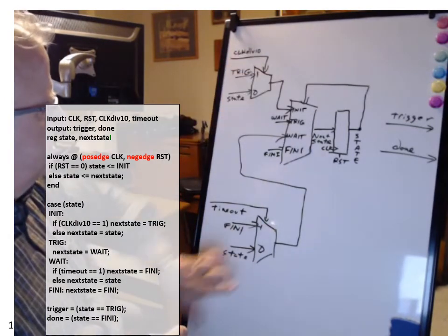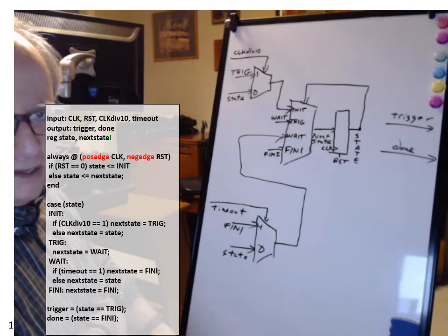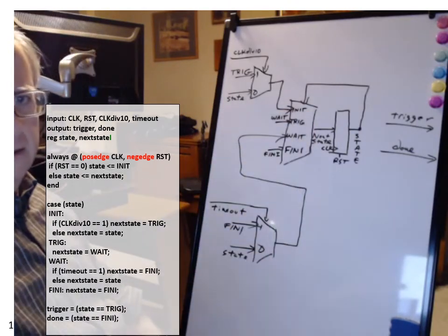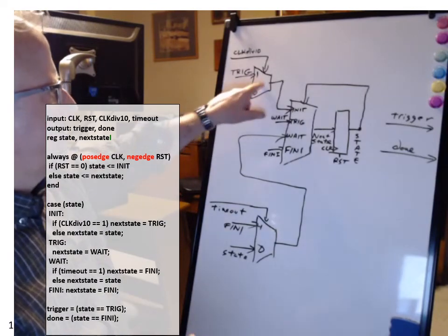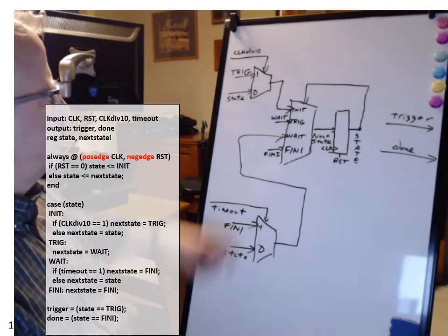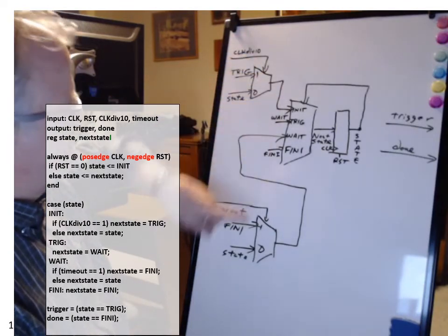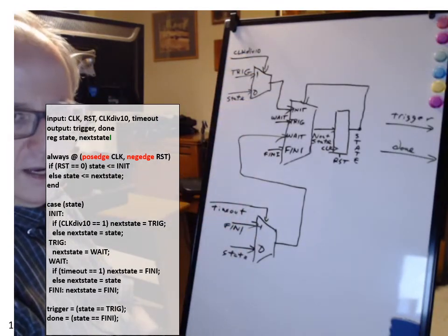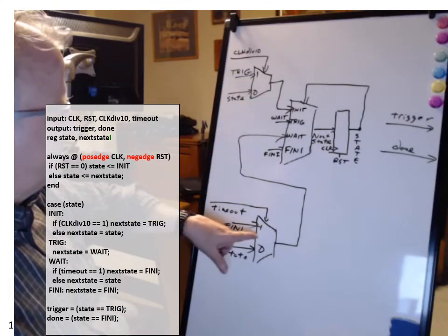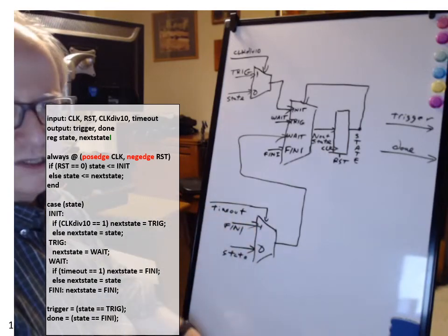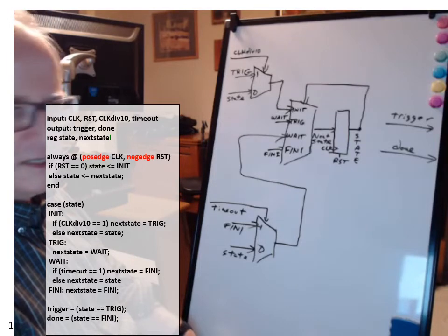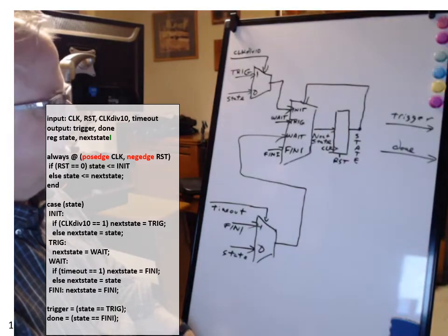And let's see what's left. We've covered all the next state logic. So what you see, a four-way case gave us a four-way mux. A two-way if then else gave us a two-way mux. And the conditional expression ends up being the control line for the mux. And then the values being assigned inside the branches of the if then else end up determining the inputs to the mux. Okay, we've got everything except the output logic.